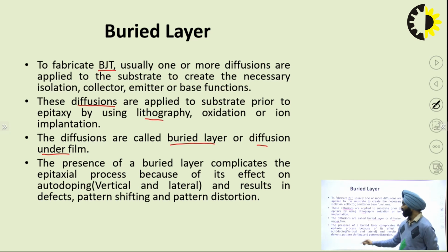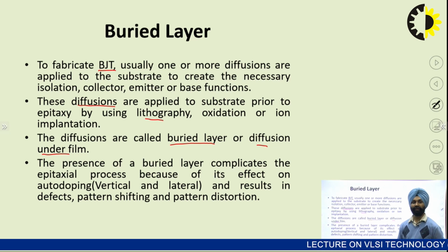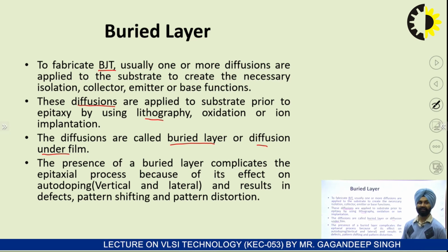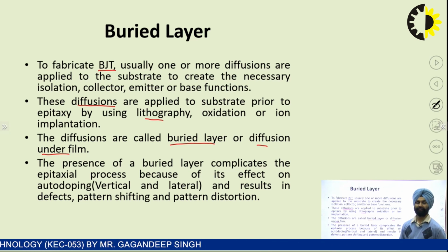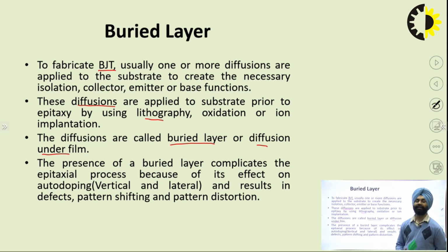The presence of these buried layers complicates the epitaxial layer because of its effect on the auto doping, and this results in defects. The defects may be the pattern shift or the pattern distortion.